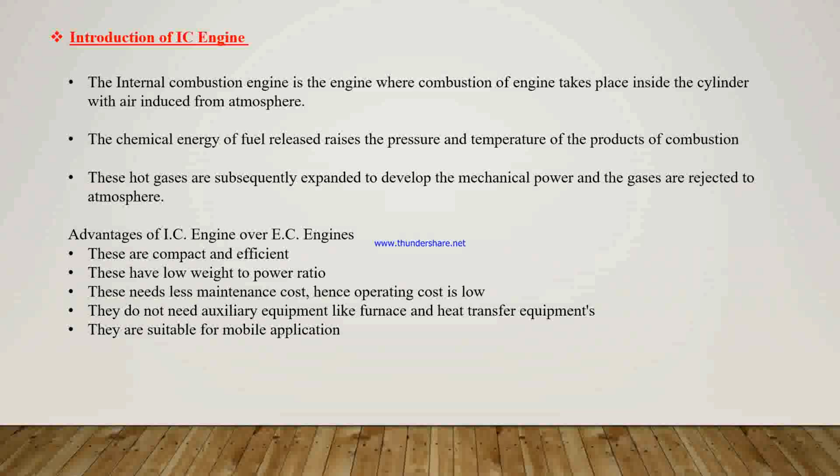The advantages of IC engines over EC engines are that they are compact and efficient, and they have a low weight to power ratio. Also they need less maintenance cost, and hence operating cost is also low. They do not need auxiliary equipment like furnace and heat transfer equipment, which are required in external combustion engines. They are suitable for mobile applications.